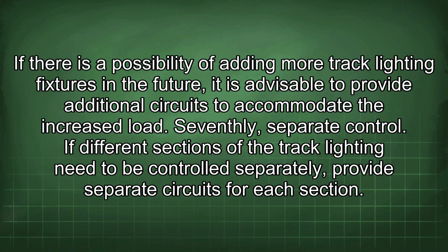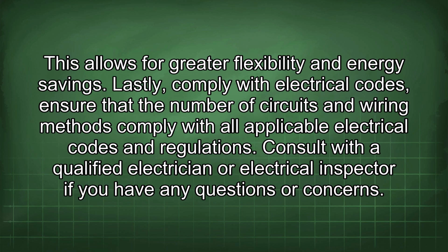Seventhly, separate control. If different sections of the track lighting need to be controlled separately, provide separate circuits for each section. This allows for greater flexibility and energy savings.